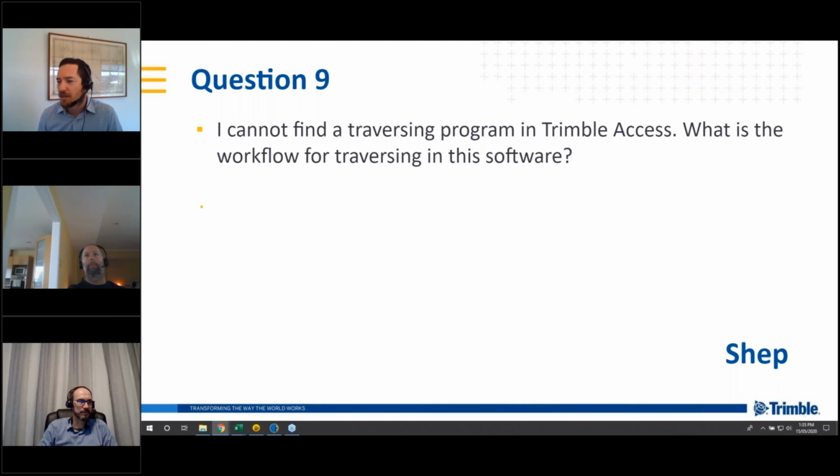Yeah, for people looking at that, I guess we use the terminology across in TBC of traverse adjustment, and then we have network adjustment, depending where you've learnt your surveying from. The traverse adjustment in Business Center is a Bowditch adjustment, or Bowditch, depending on which part of the world, or transit is the other terminology, transit compass method.